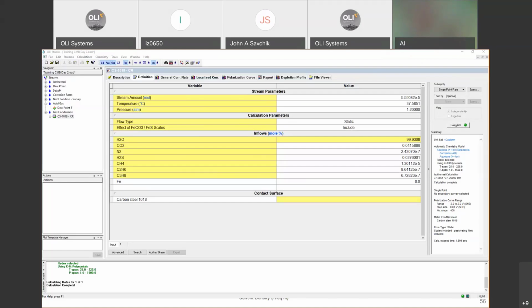And there is another question: the repassivation potential is not in the plot. I think this result comes from cyclic voltammetry. We do have an equation for the calculation of the repassivation potential. In fact, I can share with you a paper that I was reading yesterday, just to make sure that I fully understood the calculation of that repassivation potential. I will share that paper with you, where we show exactly how we calculate that.